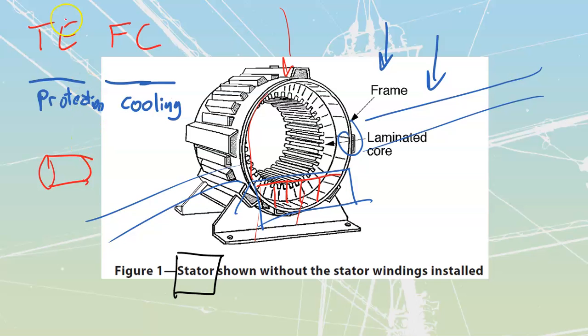I'm going to have the motor, and then around the back end of the motor, there's going to be another shield that's stood off from the motor, maybe about a quarter inch or something like that. That shield at the back end of the motor is going to have a small shaft extension with a centrifugal fan, and it is going to pull air into that centrifugal fan, and then force it up and out over top of the motor to cool that motor down. We're just using forced air to run that one down.